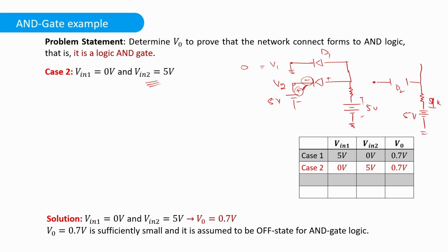Now what happens with the first diode is that we can see due to this positive terminal, which is the internal battery source, this positive terminal becomes connected with this positive terminal. So we get the diode to be in the forward bias condition because same terminals are connected with each other. So due to that, this diode will actually act as a 0.7 volt source because that is the value of voltage dropped across a diode.